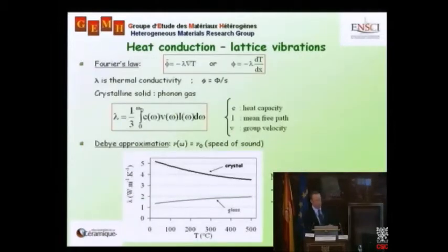Now, lattice vibrations not only control the heat capacity, they have a very important role for heat conduction. Let me remind you of Fourier's law: the thermal conductivity is the constant of proportionality in Fourier's law, which determines the heat flow under a thermal gradient, dT/dx.